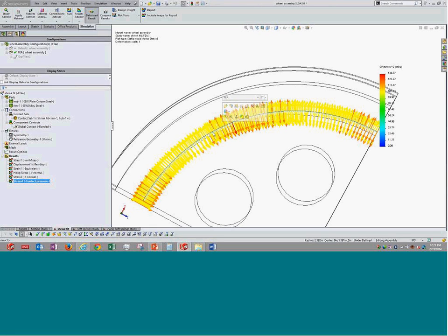Those are represented by this contact pressure. So whenever we plot this contact pressure, it shows us the forces that might be present between those two surfaces. Otherwise, if it is a no penetration contact, this plot will also tell you, when one part comes and interacts with another part, what kind of forces it is going to exert on the other part.